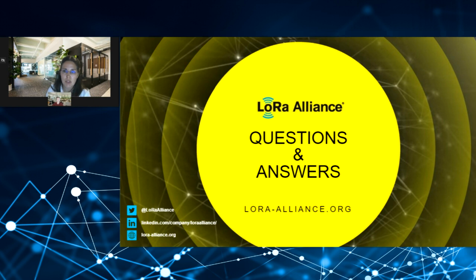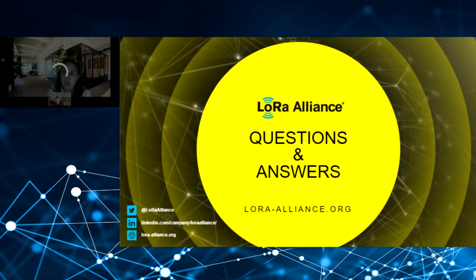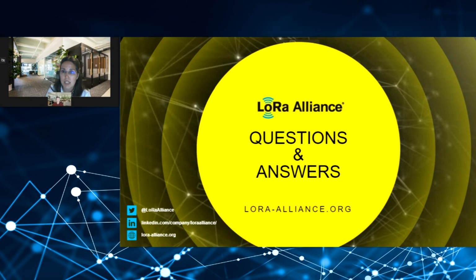Important here for the setup on the gateway side is that you should always use a gateway or a setup with all channels support. So this means for US, for example, you need a 64 channel setup in order to be able to get all join requests sent by the device. Because the goal of this testing is to ensure that the device follows the limitations already defined in the LoRaWAN specification. So the gateway, it's important to ensure that the gateway is able to receive all the join requests sent.